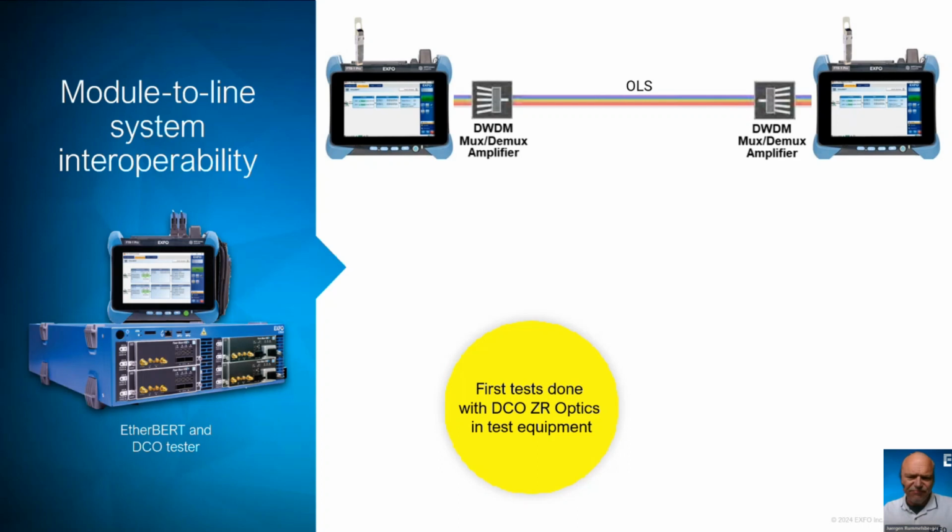But since we cannot measure an infinite number of bits, and it's really impossible to predict with certainty when errors will occur, the confidence level will never reach 100%. So a pragmatic value here would be 95%, and this gives us a factor of around 3, by which the test time must be incremented.